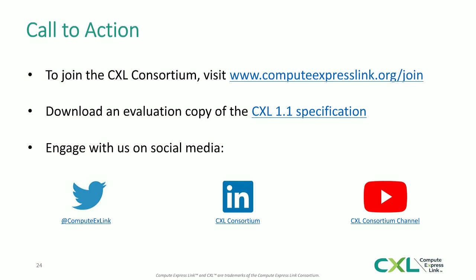Another question is, is it possible to interleave multiple CXL channels to improve CXL bandwidth usage? So I'll take a first shot at this as well. The interleaving mechanisms are really application specific and implementation specific. Having said that, there's nothing in the spec that precludes you from enabling interleaves across devices or even within the devices themselves. So it's really an implementation choice.